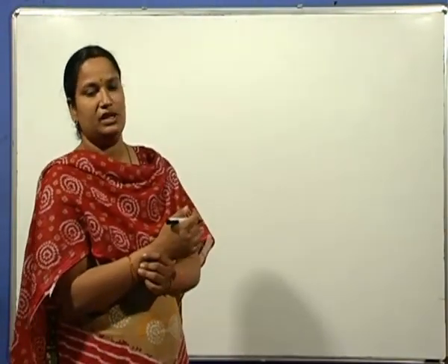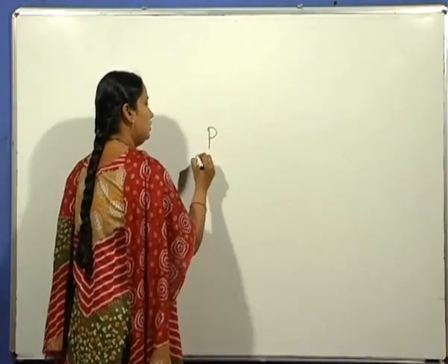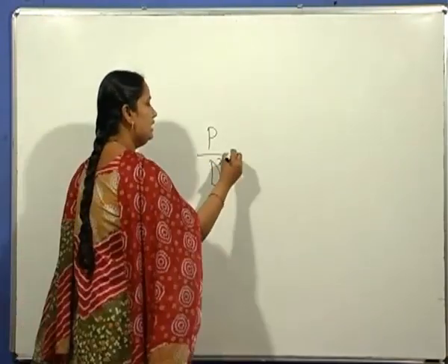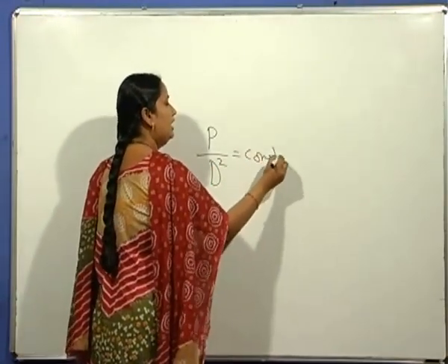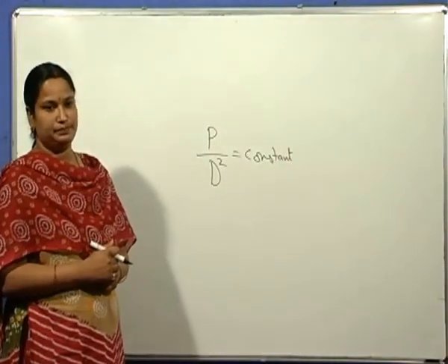Another disadvantage of Brinell hardness is that unless the load divided by the square of the diameter of the indenter is maintained constant, the Brinell hardness will vary with load for the same material.